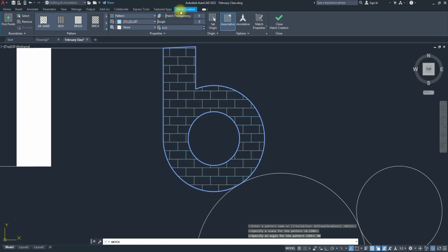Then the other thing you also have is your transparency level. That transparency level lets you decide how faint you want it to be. Transparency is usually between 0 and 90. AutoCAD purposely didn't make it 100, because why do you want it to be invisible? If you want it to be visible, why did you create it in the first place?